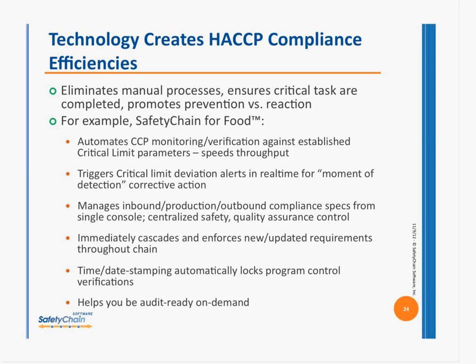One example I like to use is meat facilities that use a Tompkins study for temperature control. Oftentimes, the critical limit is 44 degrees, while normal cooler temperatures might range from 30 to 35 degrees. Why wait to hit that critical limit? Instead, send an email or text alert at 38 degrees, alerting your food safety department as well as your maintenance department, who may be responsible for refrigeration. Eliminate the need to report a non-compliant event to your HACCP program.